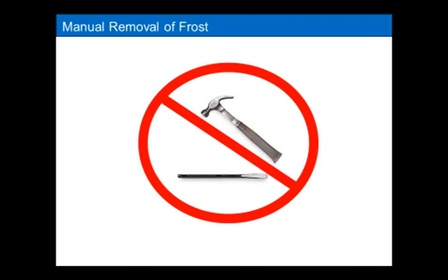And let me give you some real-world advice here. Don't go crazy when it comes to defrosting these coils. Do not take a hammer or a chisel to chisel away. Don't take a screwdriver to break away the ice. It's very, very easy. We've all done it. A lot of technicians have made this mistake, unfortunately, including myself, where we've rushed the process of defrosting some of these coils, got a little bit too aggressive, and nicked the coil enough where the refrigerant started to leak out of the coil. And that's one thing you want to avoid by all means.